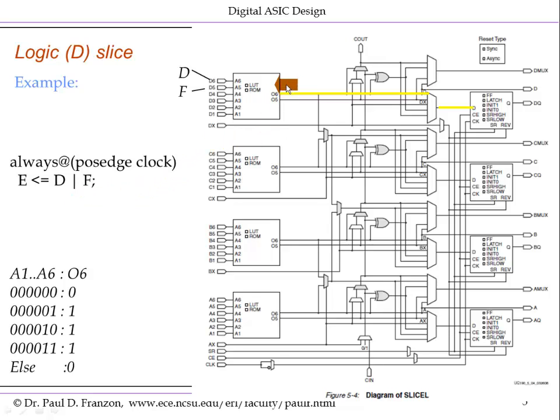Notice I can fit more logic in here. I have another logical output that could still be programmed on top of this. Also notice that by only having one logic gate here, and this isn't meant to be terribly general, I basically built the equivalent of one logic gate using this 256-bit SRAM.